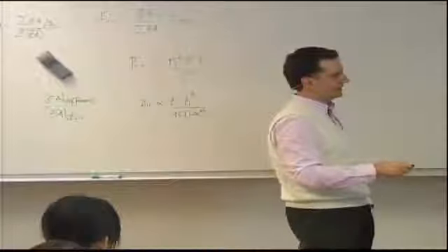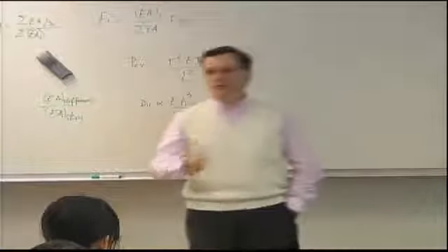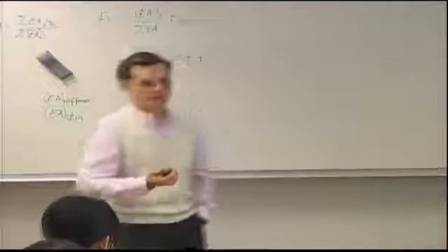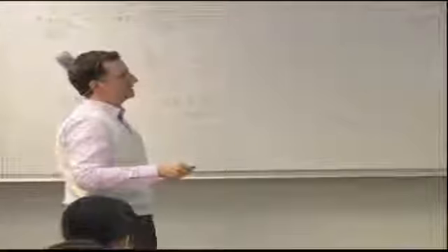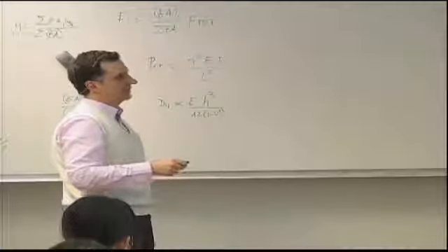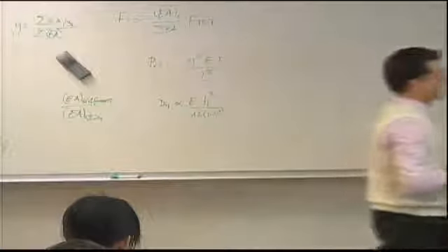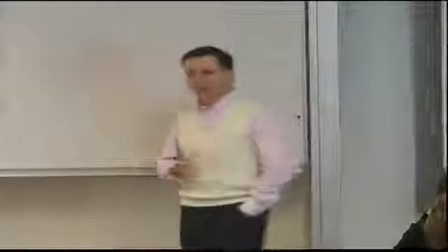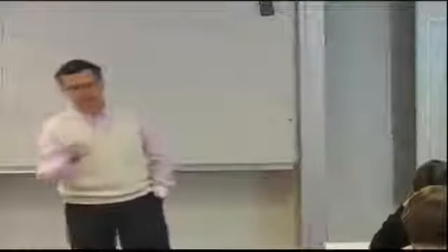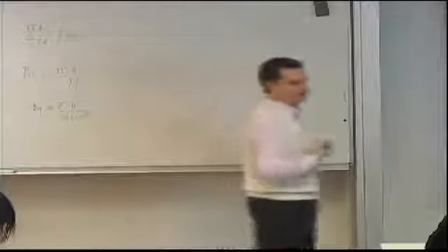Protruding head fasteners like these start approaching essentially the clamped condition. Remember, for the clamped condition, this C would be 4, because the buckling load in clamped beams is 4 times that of simply supported. So we are a little bit before the clamped case, and it's a factor of 3, which is purely experimentally determined. There is no magic about analytically finding that the value is 3.